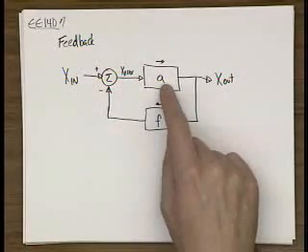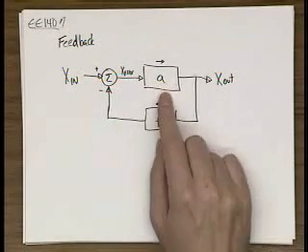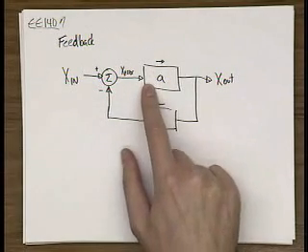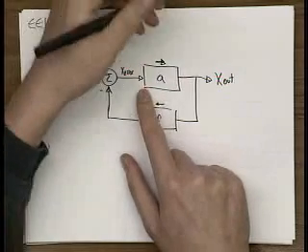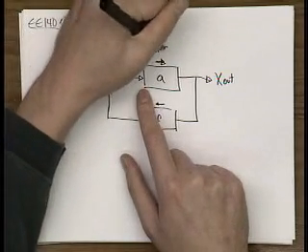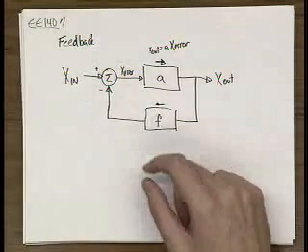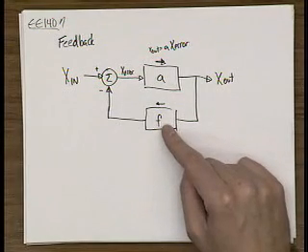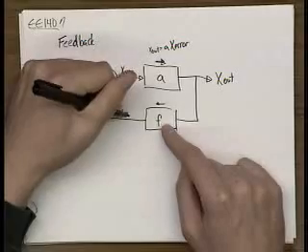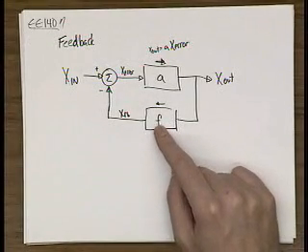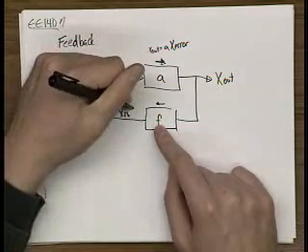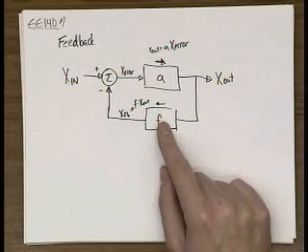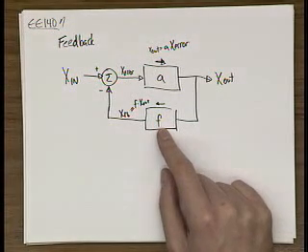You've got a forward path gain, a gain circuit A that has a gain of A. And I drew this little arrow to indicate that the direction of the gain of this block is purely unidirectional. This means that X out equals A times X error. It's a purely unidirectional ideal network. Similarly, let's call this XFB. You've got a feedback network where XFB is equal to F times X out. And again, the assumption is made that this is purely unidirectional. In reality, that never happens.